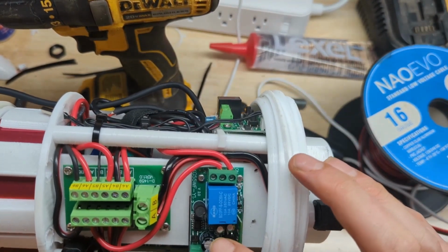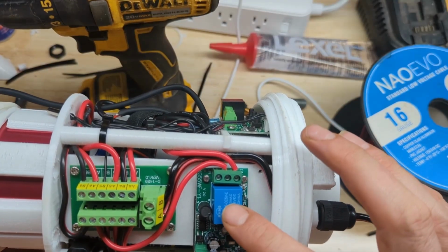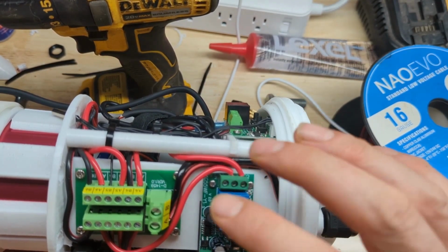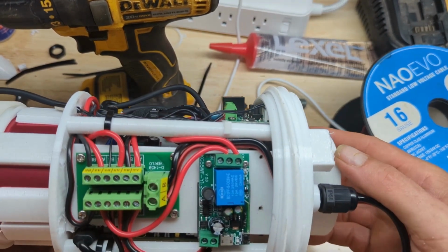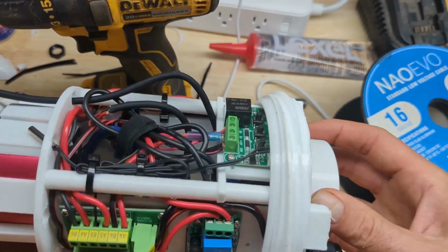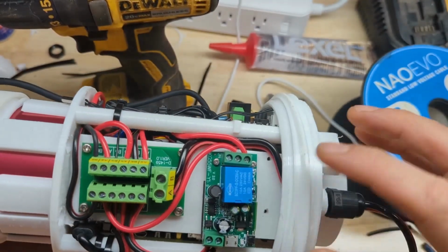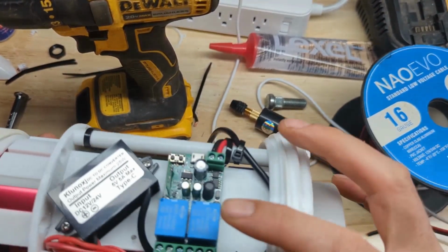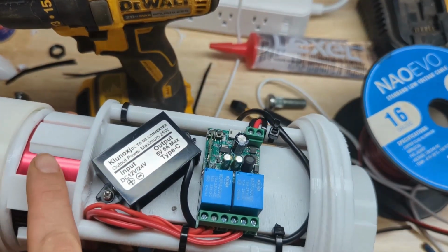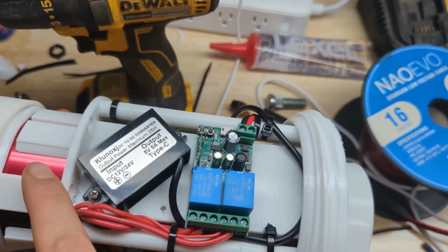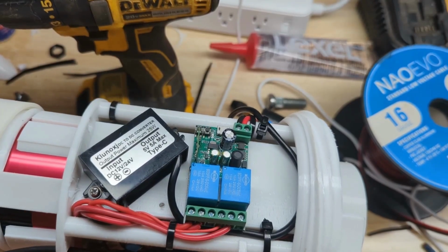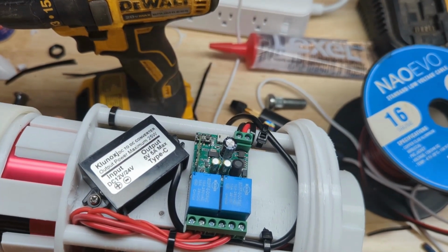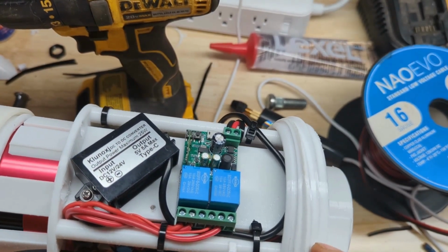I think the capacitor does not hold enough charge, so when it's actually firing up a component, one of the switches, the dew heater, when it starts, it's generating heat, so that's obviously going to pull a little bit more power than, say, the camera would on its startup. So whenever it first clicked on, it was actually causing the camera power to fade out, and that would cause the camera to drop briefly, just long enough that the Raspberry Pi thought it was offline. And the only thing that corrected that was rebooting the Raspberry Pi. And of course, if everything else was already on, no other issues.